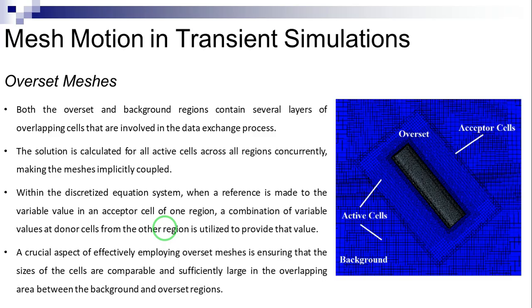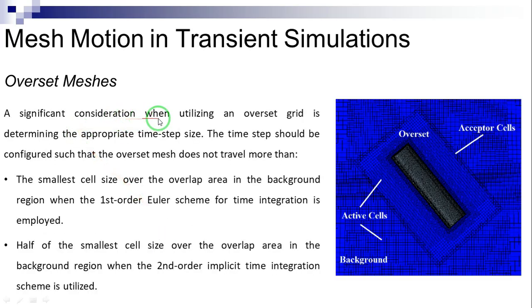A significant consideration when utilizing an overset grid is determining the appropriate time step size. The time step size for an overset simulation is contingent on the mesh size.